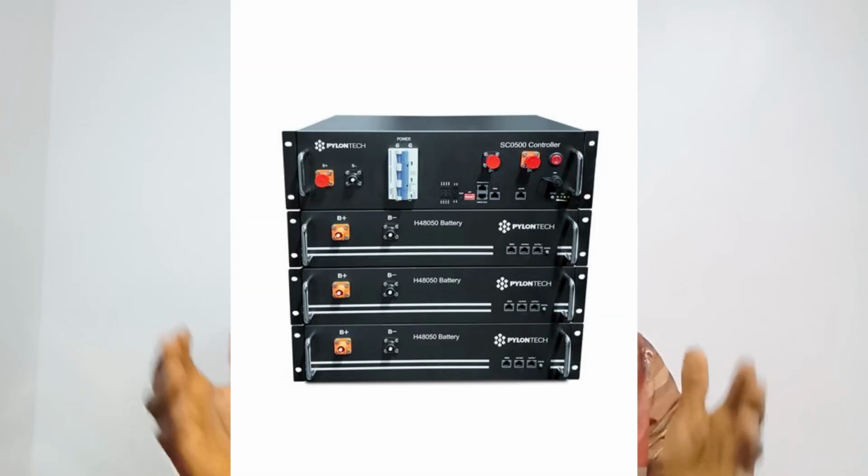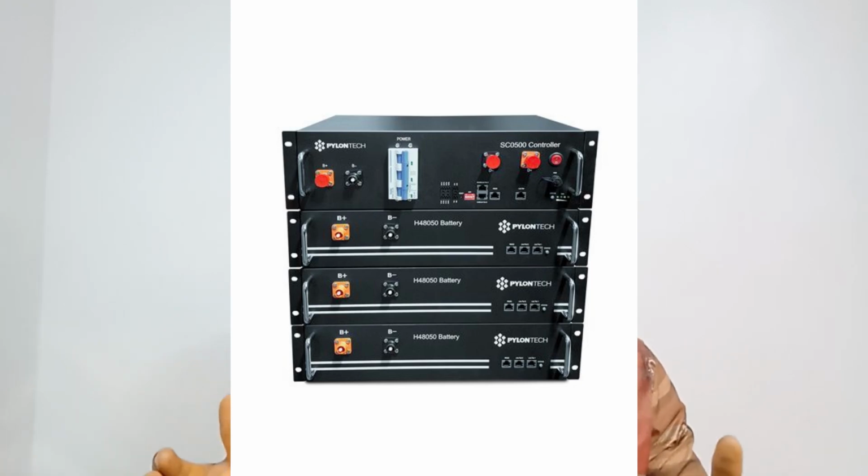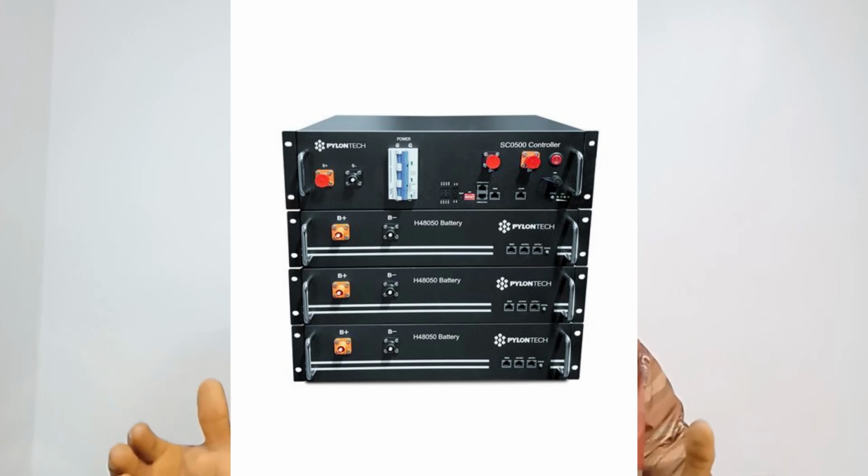Then we move into the second type of lithium batteries, which is the lithium iron phosphate battery. The lithium iron phosphate batteries are safer to use, more durable, more thermally stable, and have a longer charge cycle, between 3,000 to more than 8,000 charge cycles. They have a smaller energy density compared to NMC batteries.